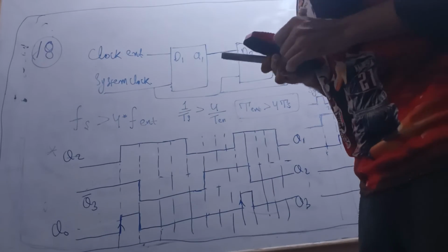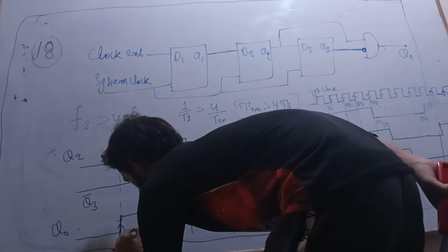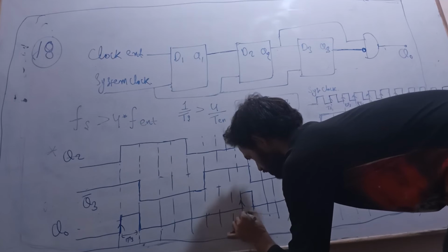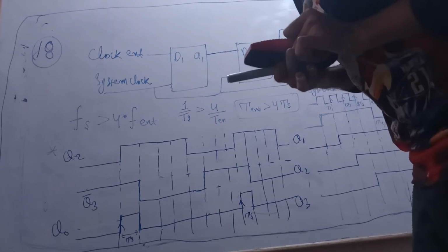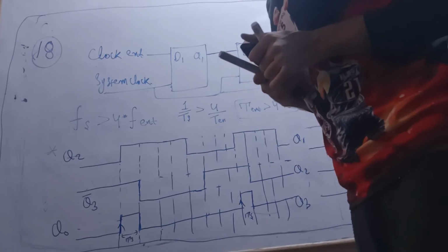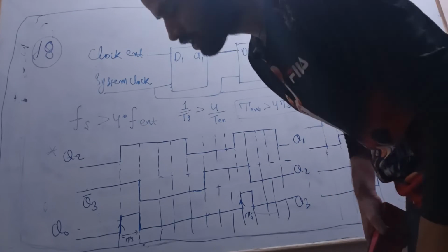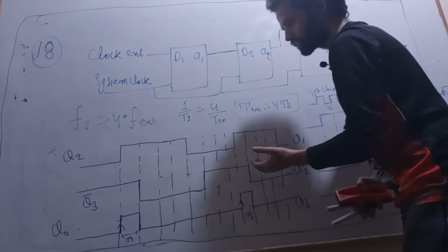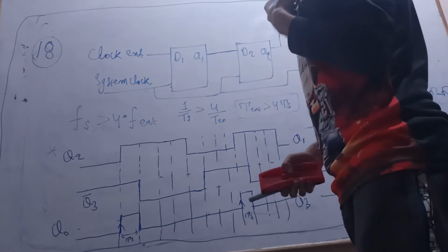Now the option is what? It is rising edge. Rising edge, the duration is what? TS duration. So this is nothing but a rising edge detector with pulse of Q out, equal to 1 cycle of the system clock. It is a rising edge detection.